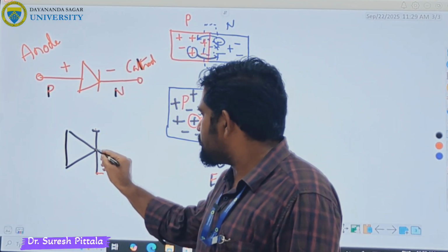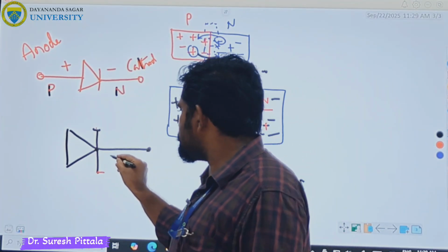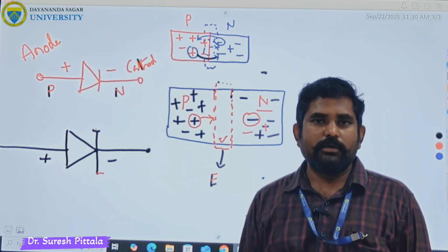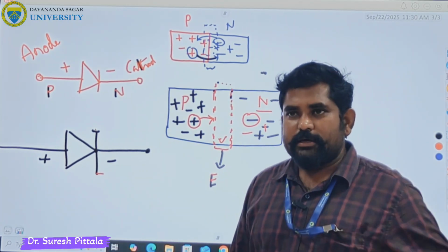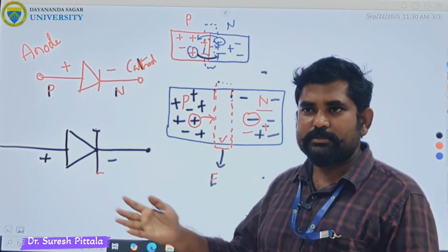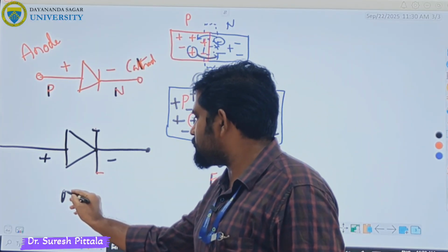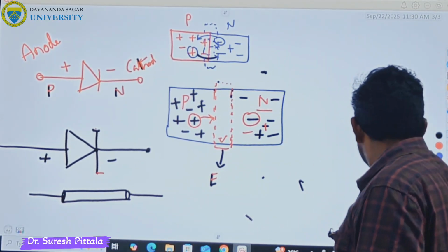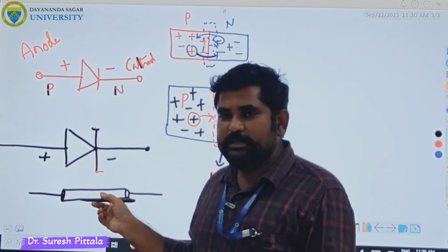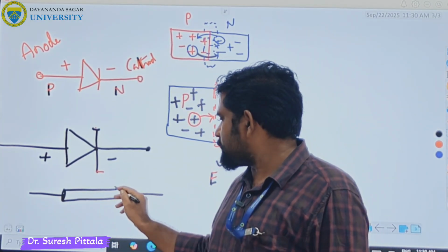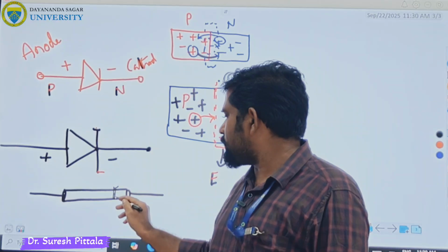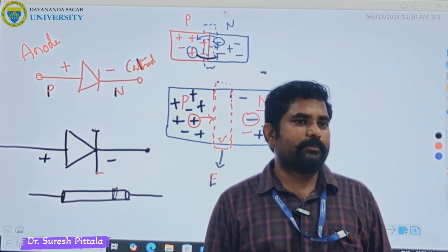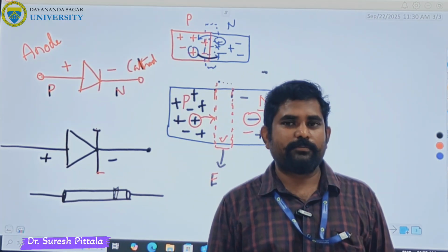Correct. So again, this is the negative side, that side is the positive side. Okay. So when a Zener diode is given, it won't look like this. It may look like some pen, or sometimes like this it will be. Then you should know which side is positive and which side is negative. Always when a Zener diode is given like this, they mark something, some color, yellow or white or black, something, most of the time black. How do we remember which side is positive and negative?